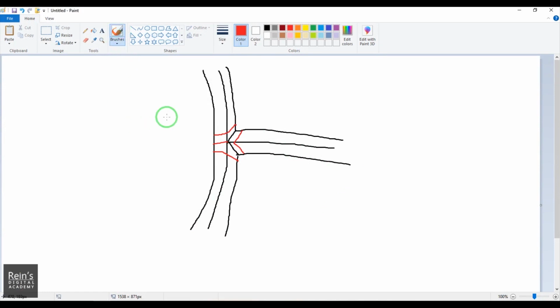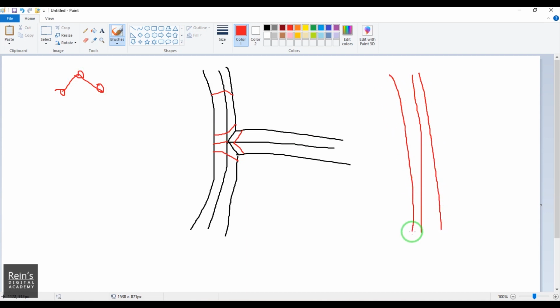So firstly, as I told, 3 lines are important for crease. To get the crease I need 3 points. So that's the reason there are 3 lines here. Now the problem is when we add a T junction there, you get this kind of flow, which is basically not recommended.